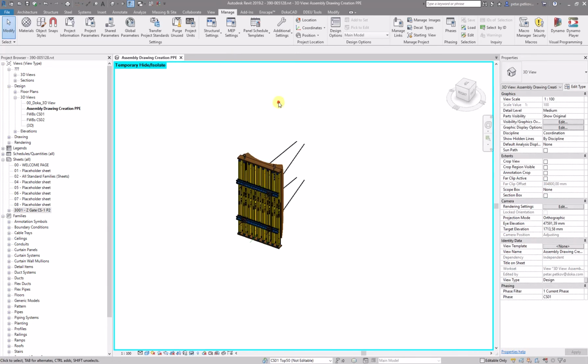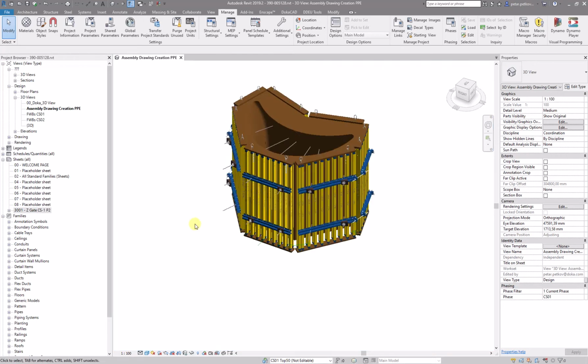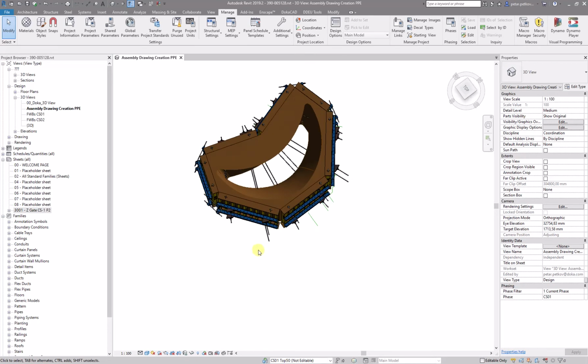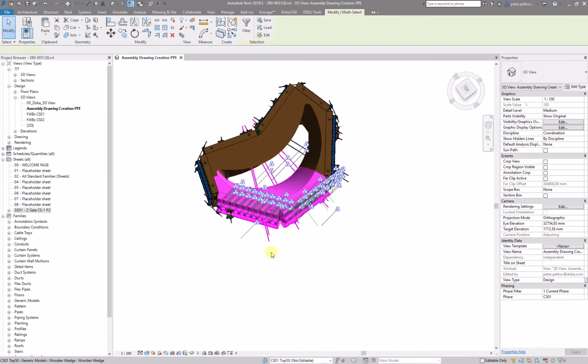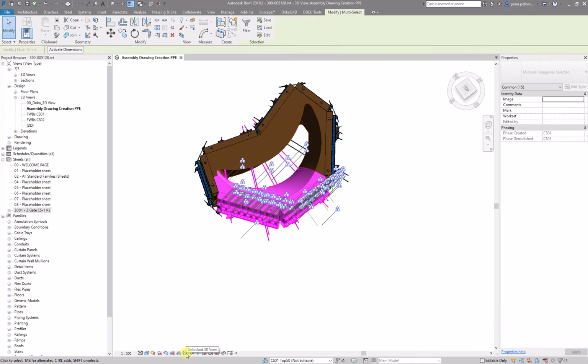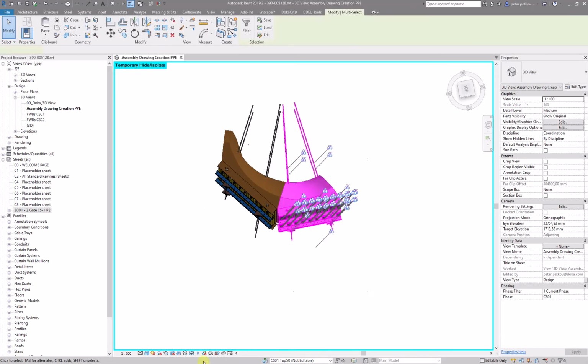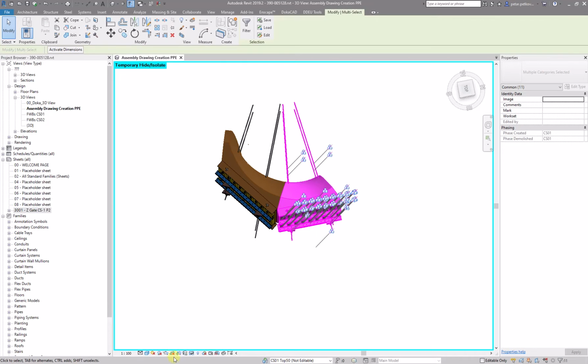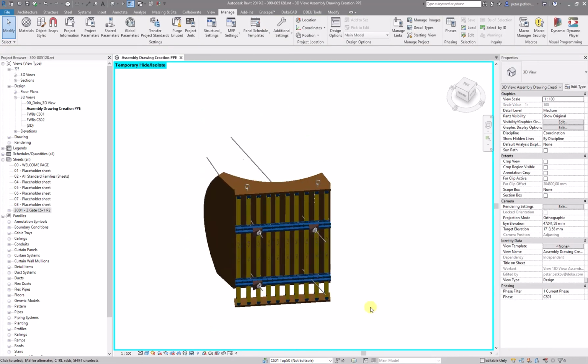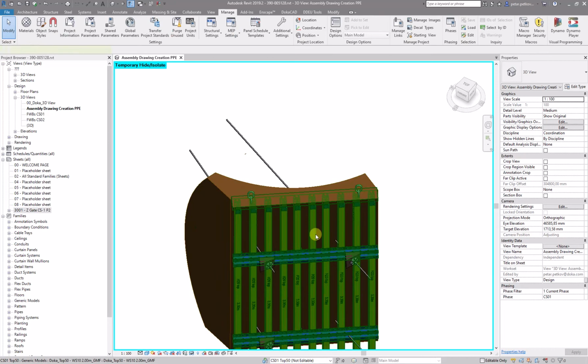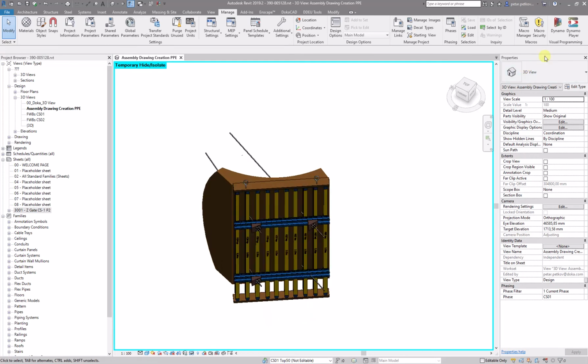Close this original one, then we unhide again from some of these buttons. We unhide all the panels, and we isolate only the ones we want with temporary isolation. I have a shortcut which is number 2, but if you want to use this one, the glasses, you can say isolate element. Then, if you don't want to see this part, you can say glasses, hide element. So this is what you want to see. You want to see a box, the top 50 panel, a box, and a small other materials.